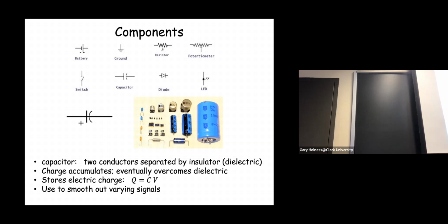And in fact, if you're doing electrical work, things like your washing machine that has a huge motor that can store charge, you want to make sure that your appliances have discharged, because even if you switch off your electrical panel, you can still get a pretty nasty shock because you have all of these appliances storing charge that need to discharge before you can do your electrical work. Any questions about that? No?